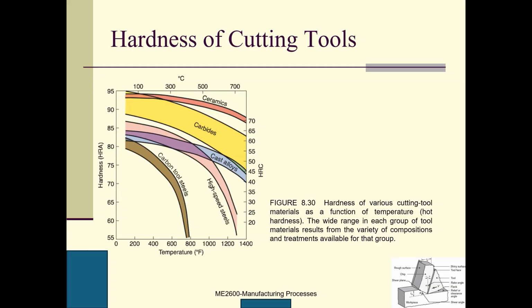Scale A, scale B, scale C depend on what kind of load you are using. You will know this later, but I want you to know this basic knowledge: HRA, HRB, HRC. And Brinell, BRINELL, is called HB. That is another way to measure hardness.